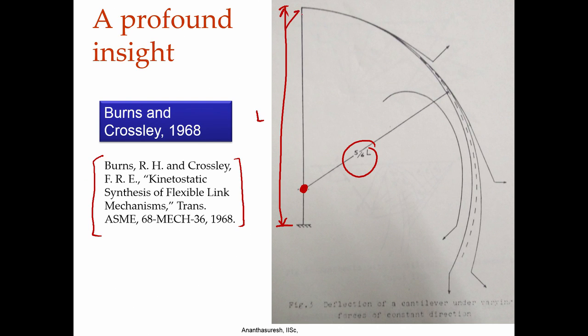in all kinds of directions, because we said that when an elastic segment is part of a mechanism with rigid bodies or other things, at the end there will be loads in all directions. If there is a pin joint, if there is a fixed end, there will also be a moment. In this particular paper, they consider a pin joint there. So, loads can come in any direction, meaning that there will be a transverse component, there will be an axial component. In that case, they actually have drawn these with a force in this direction, the beam may bend like that, force in this direction bends like this, force here, it bends a different way. So, for each case they have actually drawn these at that time.